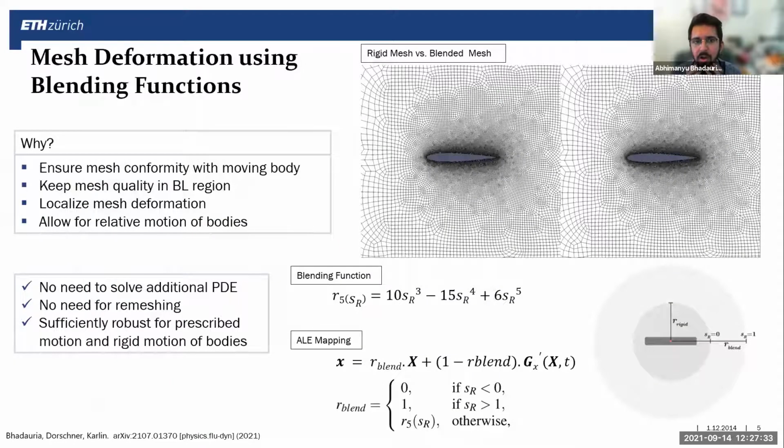So now if we're using a semi-Lagrangian approach or an off-lattice approach, which leads to conforming meshes, of course, we need to ensure that the mesh conformity remains. It's not like a standard lattice where the underlying lattice does not change. So we need a methodology to keep this mesh conforming at all times with the body, and so that the mesh doesn't degenerate as well.